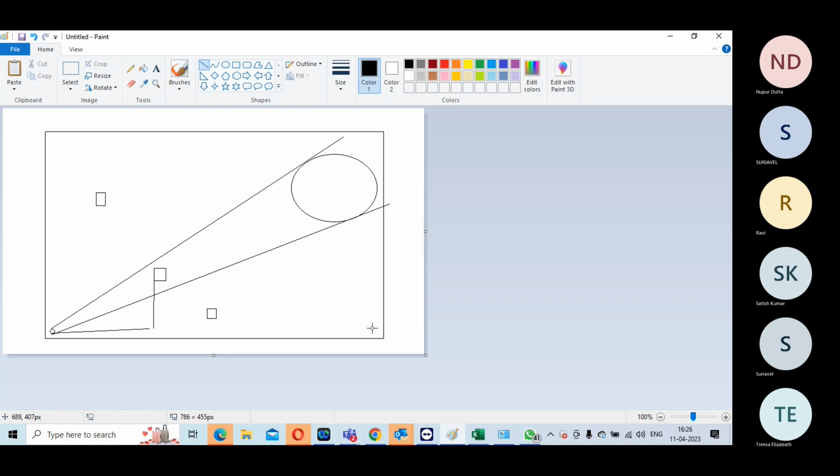Sir, one more thing, coming to the setup, insertion delay and latency. Actually, what is my thought, I don't know whether it is correct or wrong, please correct me. Insertion delay we mention at the CTS stage, when it is adding the buffers to the clock tree building. The latency comes into the picture when it is doing optimization. Is it right?